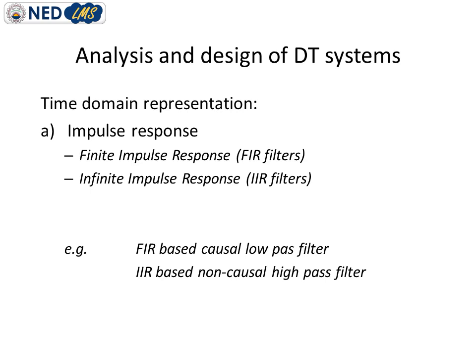Or in other words, we can say a system whose current output depends upon previous output samples is an IIR filter. We can also say that IIR filters have some feedback, because their present output depends on the previous output sample, and the previous output sample is fed back to the system as an input.